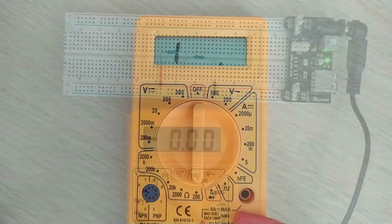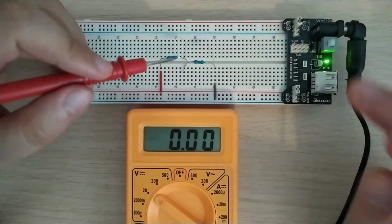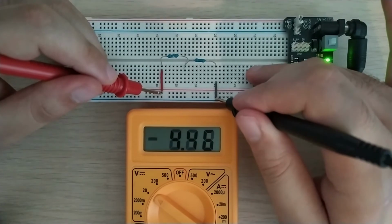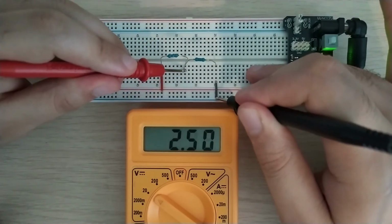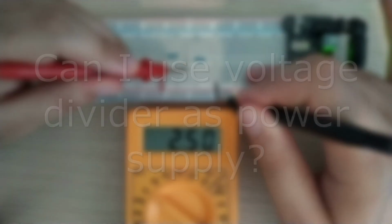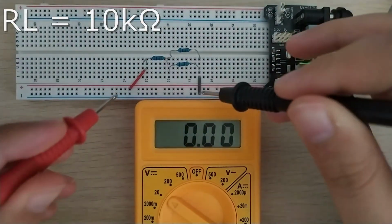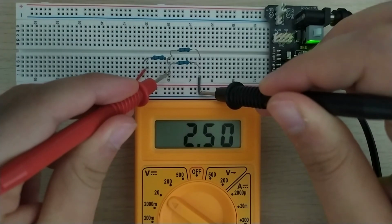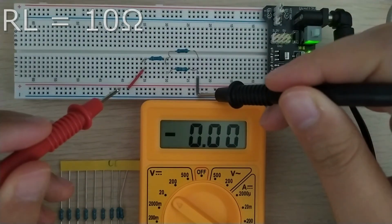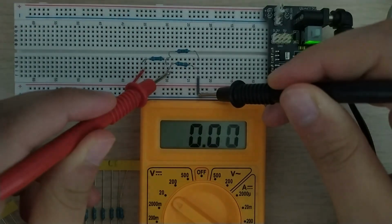The first typical use of a resistor is as a voltage divider. In fact, if we connect two resistors in series, we can have a calculable output voltage. So, with this circuit, do we create a stable power supply? Unfortunately, no. In fact, the output voltage strongly depends on the load resistance. As you can see in this video, if I change the load resistance, the output voltage changes as well. This is bad behavior for a voltage source.